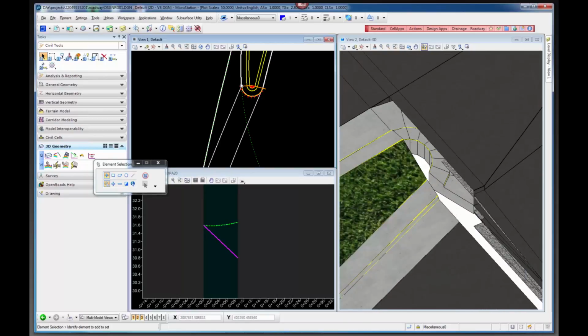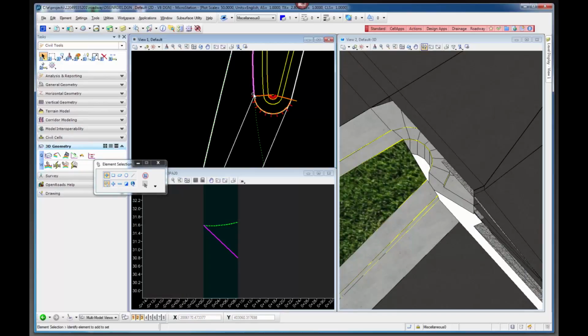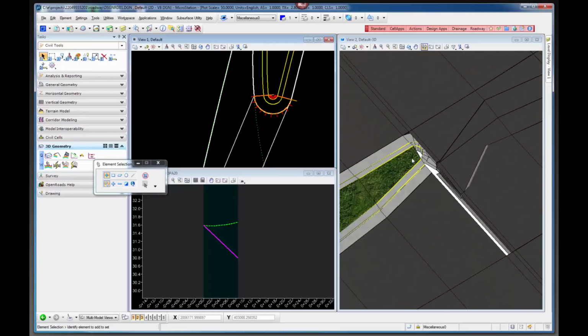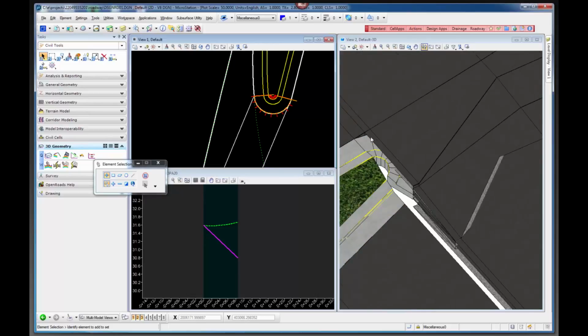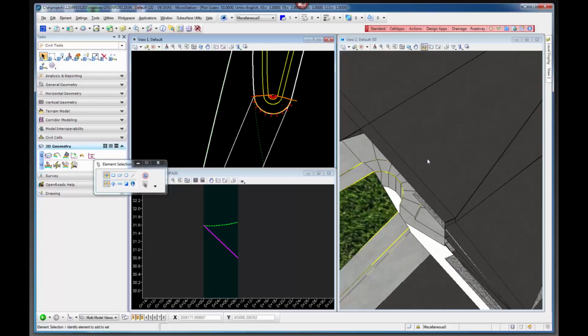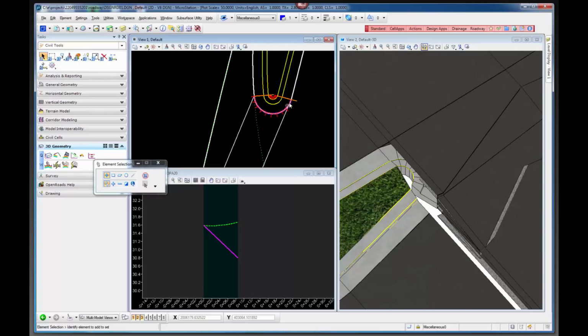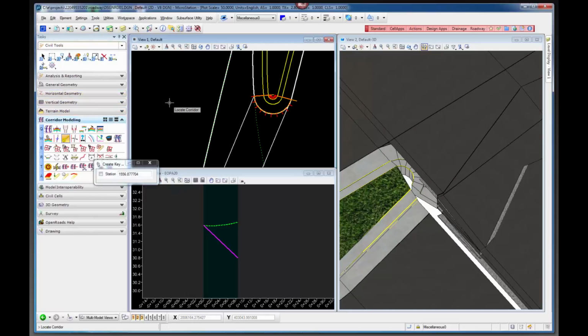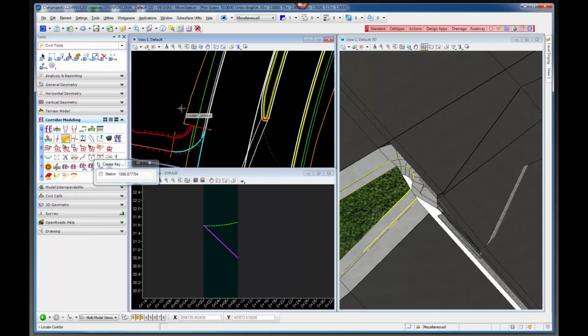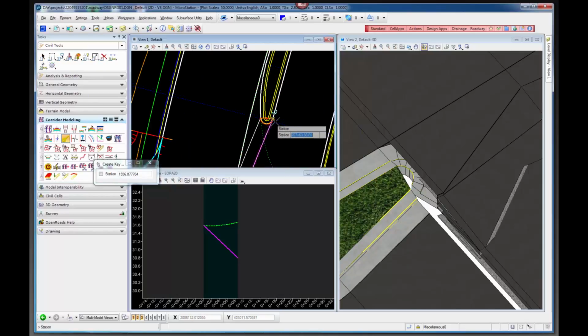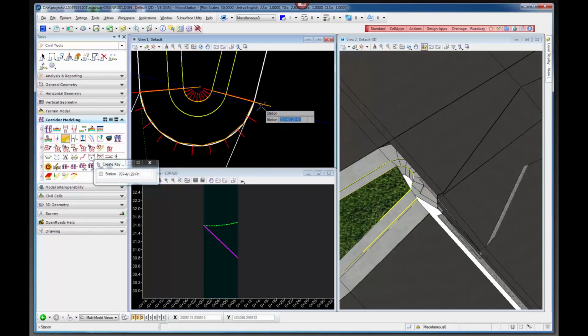And the other thing is that because the corridor basically stops at this point back here, I'm not getting that little extra gap there. So there's a little additional modeling as far as that goes. But that's what you're going to do for the noses. And again, on this one here, I would also want to put in a key station close to the end there. So I'll go to the key stations here. And sometimes it can be a little tedious adding this extra detail, but it's all in how much you want to have in your model.